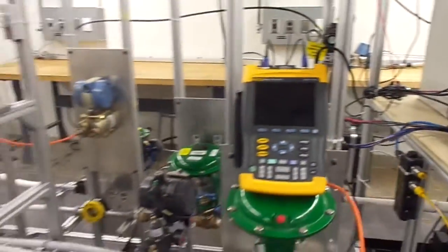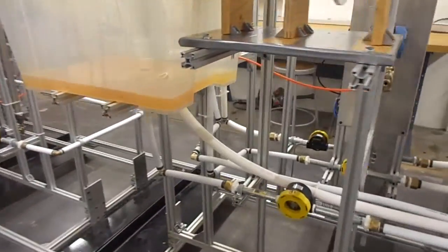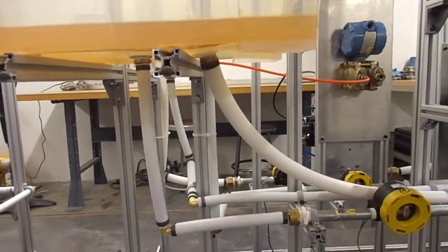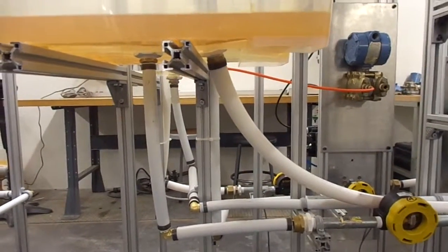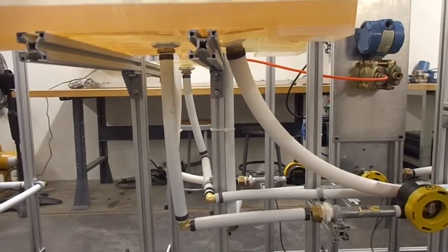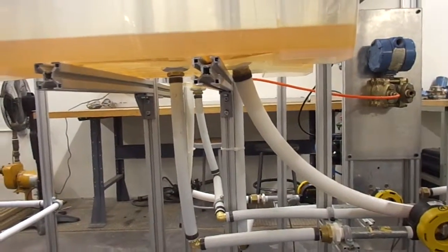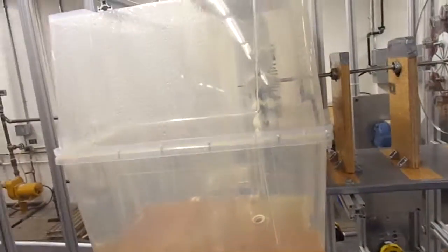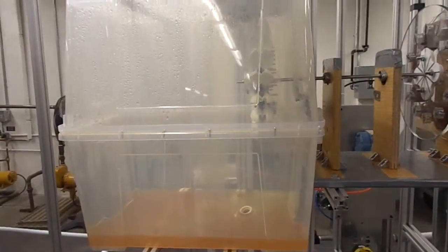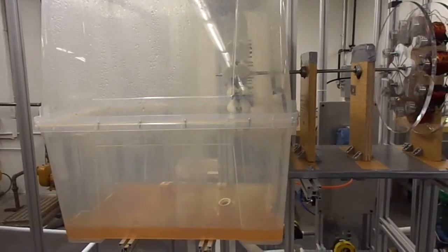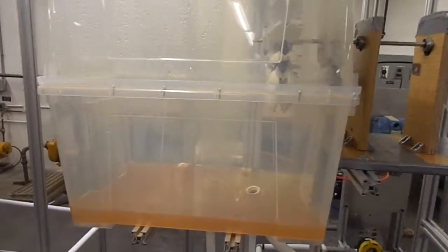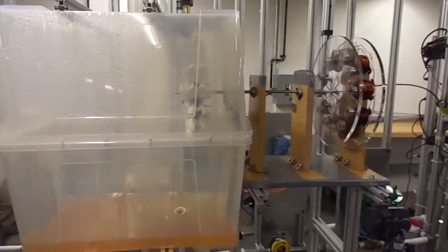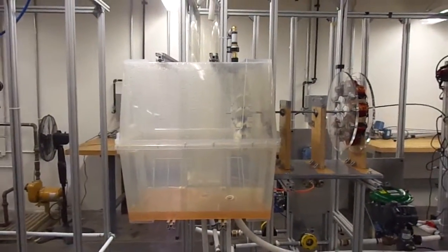Looking at the drain of the tank of the generator, we use two drains basically. One is the 1-inch pipe, which was initially the one we used to drain the tank, but since the inflow was way higher than the outflow, water was accumulating, and hence we put another 1-inch pipe as a second drain to the same tank, and that's how we were able to overcome the building up of water issue.